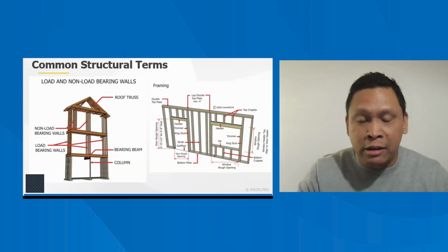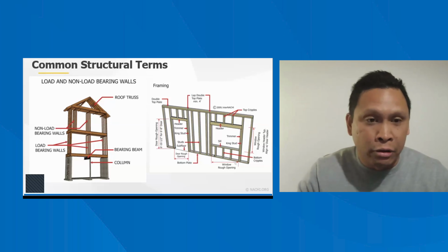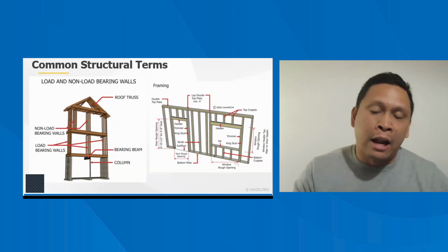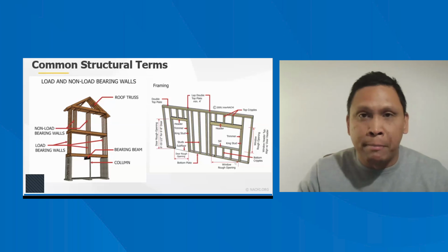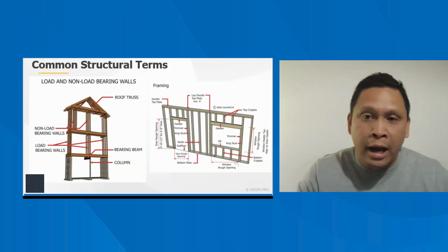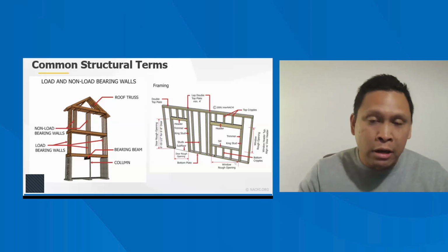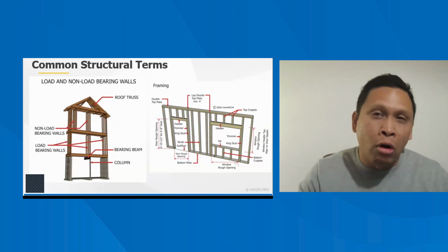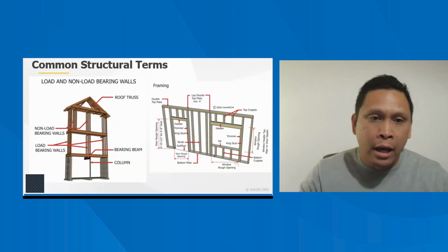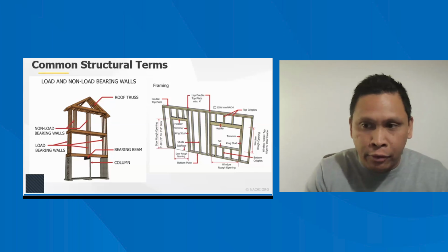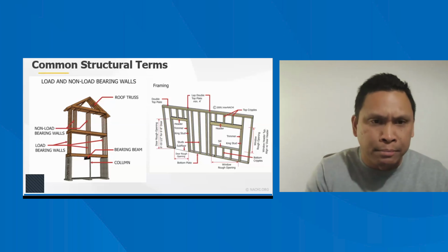And then again, if it's not cut long enough, then it's not helping to create a continuous load path because there's a gap. So that's another real example of why it's so important to make sure that you're taking your time in these homes, because a lot of the meaningful conditions and defects, if you will, that need to be noted and brought to somebody's attention aren't always the most easily discernible until you're there for a good amount of time.